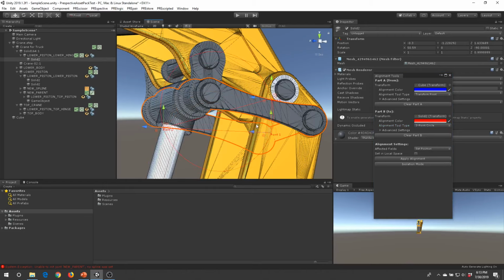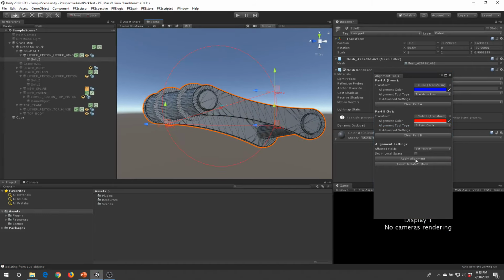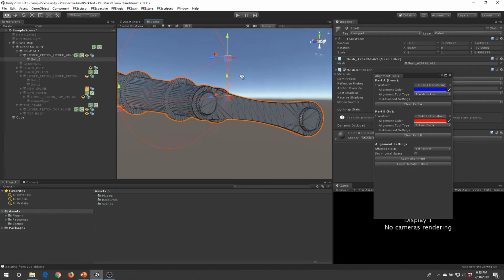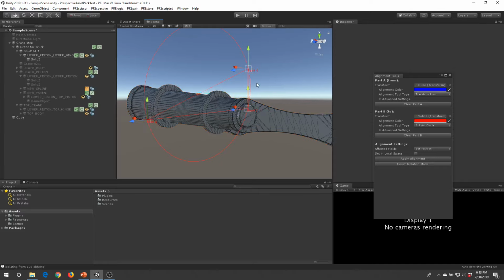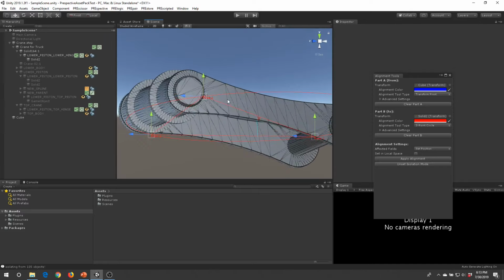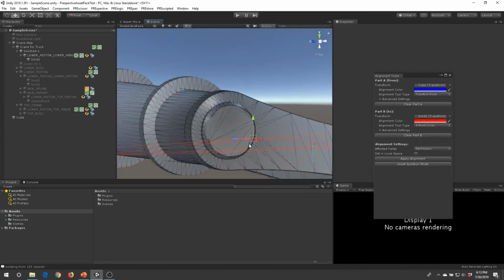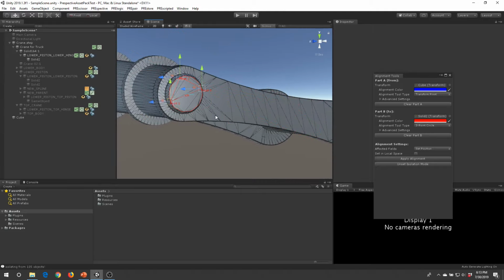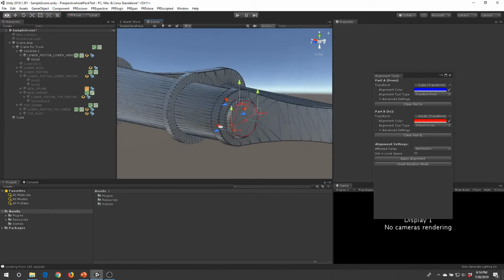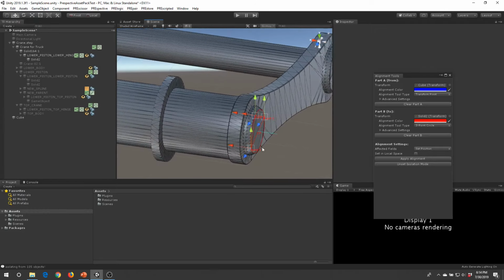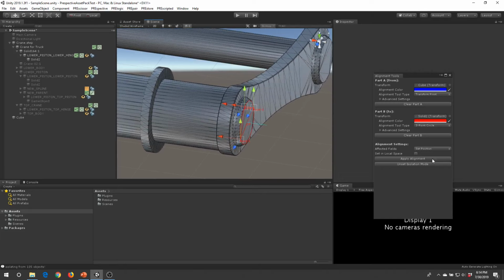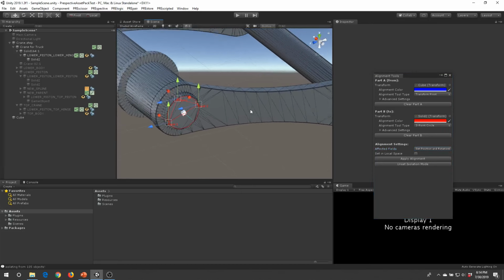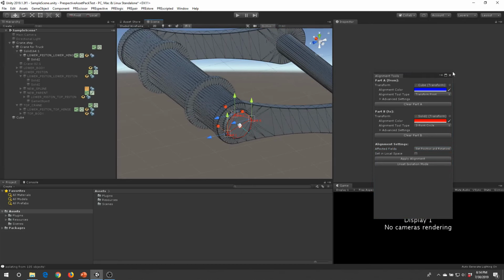And actually, I guess we could use isolation mode right now. There's a quick isolation mode selection over there. And let's do some vertex snapping. So let's move it to the corner positions. Over there. And that seems to be pretty much okay. So let's apply the alignment. And we just need to, let's set position and rotation. Doesn't really matter anyway. And let's close this window.